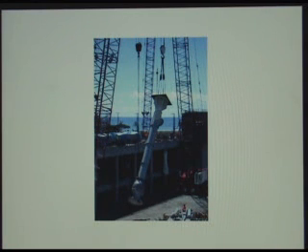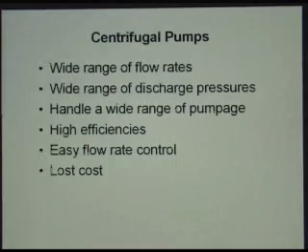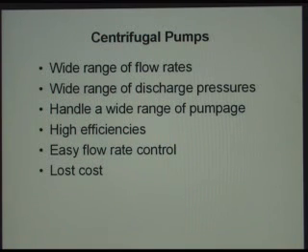So, centrifugal pumps, why do we use them? They have a wide range of flow rates, and they have a wide range of discharge pressures. They handle a wide range of pumpages, high efficiencies, easy flow rate control, and they have a low cost because there are so many manufacturers out there. We get a lot of economy of scale and a lot of competition so that we get a very good price for this kind of equipment.